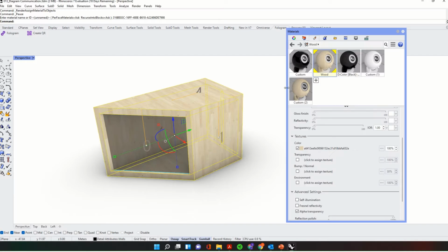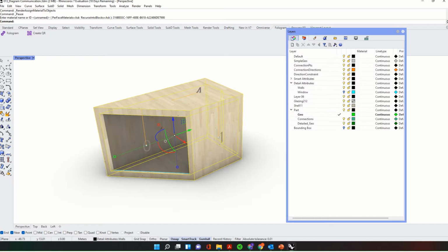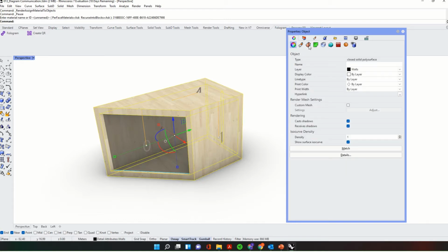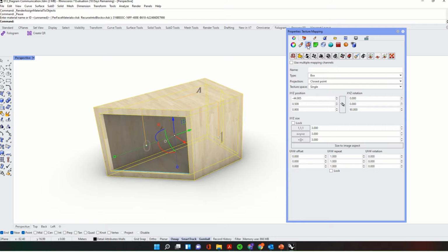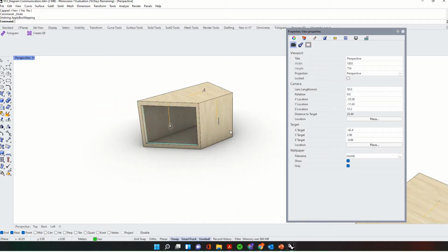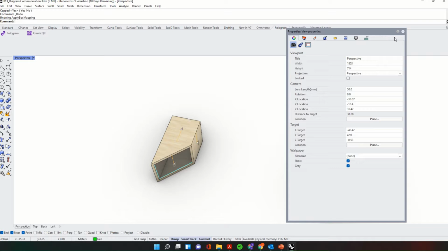One thing I'll note is that it's important to get the scale of your material correct. So if we go to properties and navigate to this texture mapping button and then box map, we can then change the scale. So if I click 4 meters by 4 meters by 4 meters and then press capped yes, you'll see the scale of the component changes. So that's important as well.